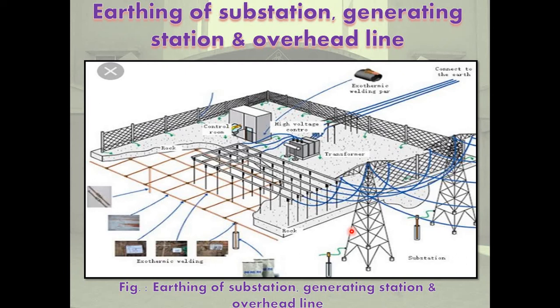The protective measures against lightning include: first is overhead shielding wires or earth wires of transmission and distribution lines. Zone of protection is 45 degrees on both sides with respect to the vertical line. Second is overhead shielding mesh for outdoor substations. Zone of protection is 45 degrees on both sides. Third one is earthing of the overhead shielding, overhead earth wire, towers or poles.